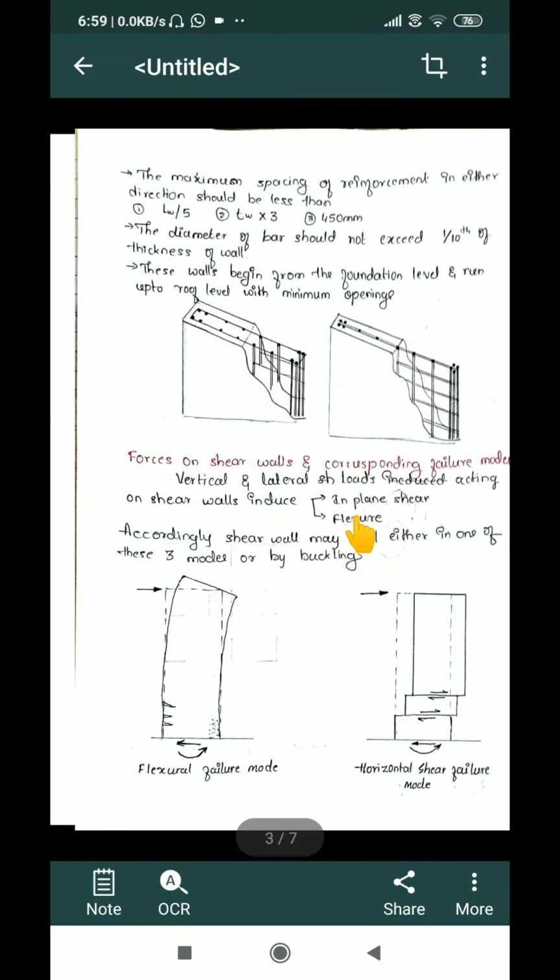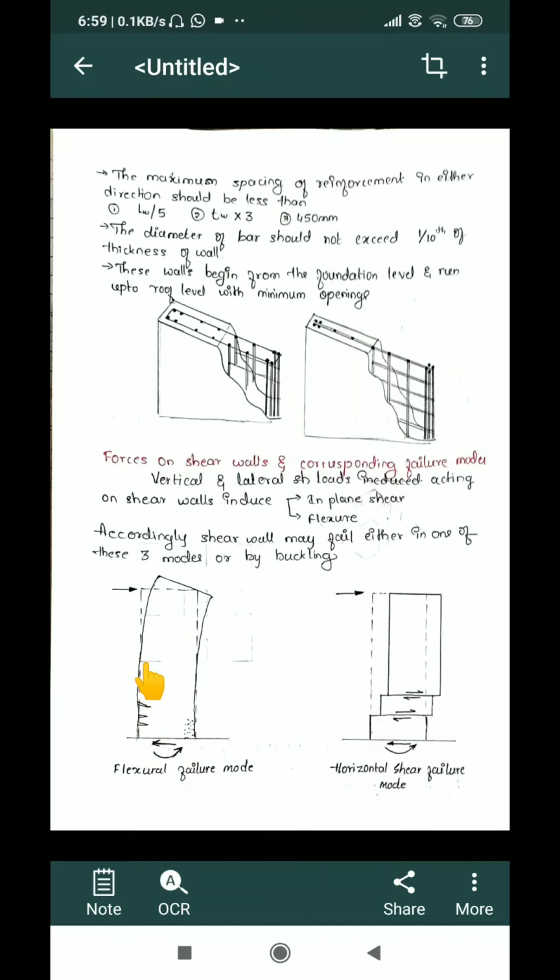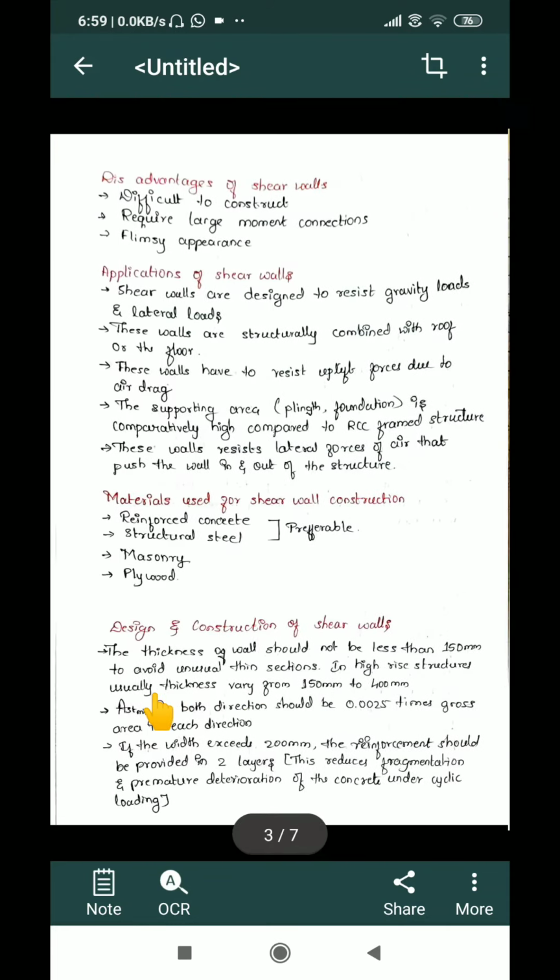So if I provide a shear wall, which is acting against a lateral loading, the lateral loads are drastically reduced because the diaphragm will provide the opposite interacting forces or resistance, and the lateral load, the force applied on the shear wall, will be considerably reduced, and hence deflections will get reduced. Because of reduced deflections, the interstory drifts are also getting reduced.